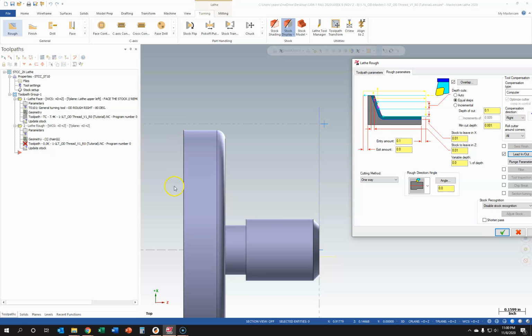When you come to part this tool off, what we'll normally use is a 1/8 inch to a 1/4 inch thick carbide cutoff bit, which is going to be brittle because it sticks out of the tool holder a certain amount so that it can actually get in here to cut this off. So with that thing sticking out cantilevered like the way it is, you have a good chance of breaking that bit, or shearing it, or just causing vibrations that you don't want while you're trying to part the tool off.